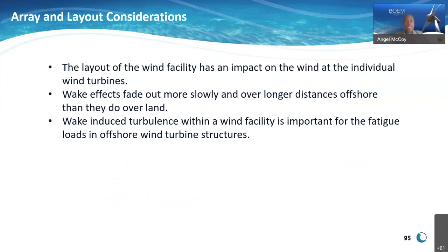So furthermore, the site-specific data helps to inform the array and layout considerations. And I have to note here that the wind resource alone does not define the layouts or the array design of a facility. It does have to do with influences from the sea bottom, other uses of the marine space, and other considerations of the users.